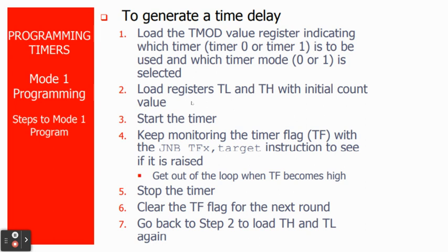And the third step is to start the timer. Of course, we can do that by giving 1 to our TR. So in C language, what we do is TR = 1;